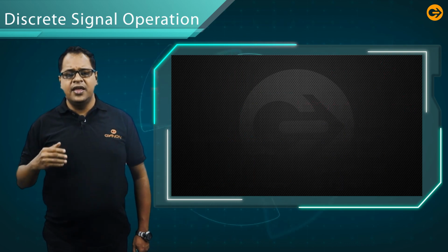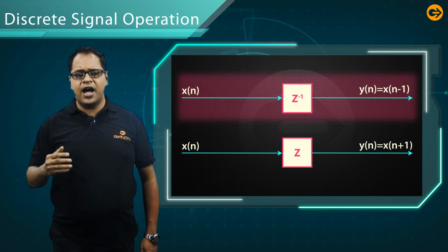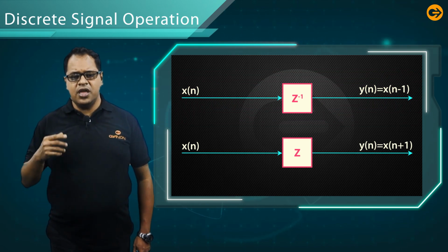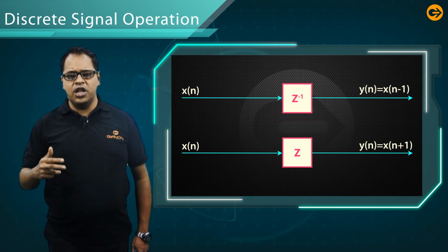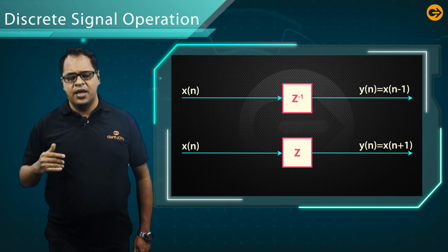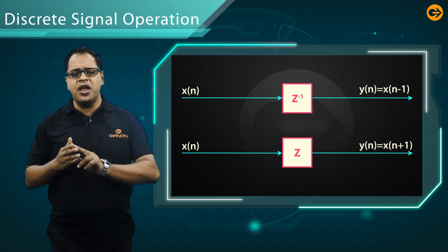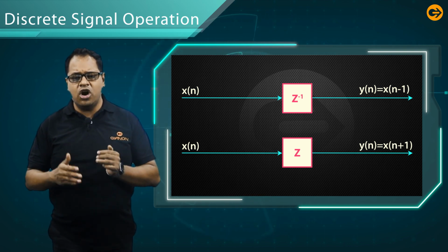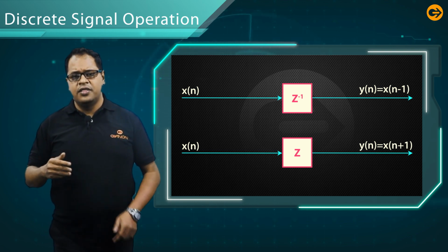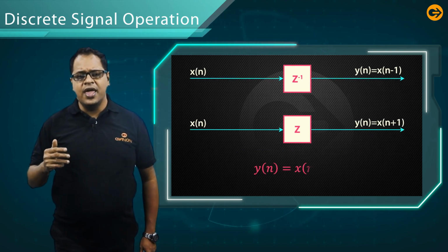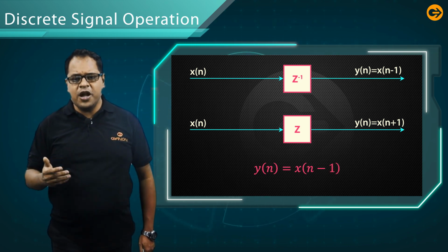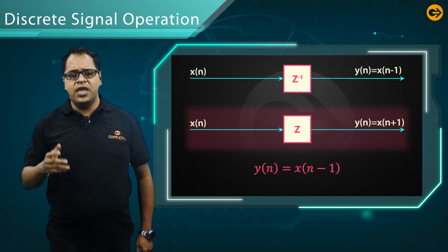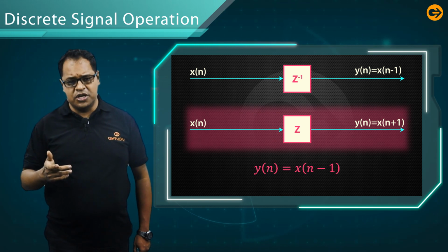Now, if the delay k is equal to 1, we get a unit delay element that delays the signal by one sample. If the input signal is x[n], the output is x[n - 1]. In fact, the sample x[n - 1] is stored in the memory at n - 1 and it is recalled from the memory at time n. Therefore, it forms y[n] = x[n - 1]. Thus, these building blocks require memory. If delay k equal to -1, we get a unit advance element.